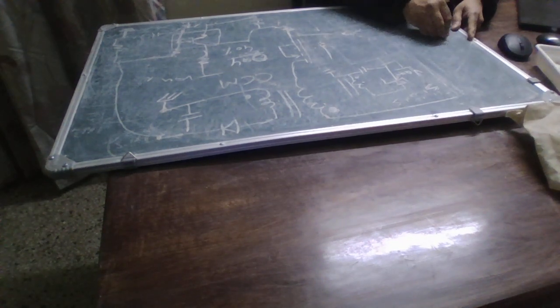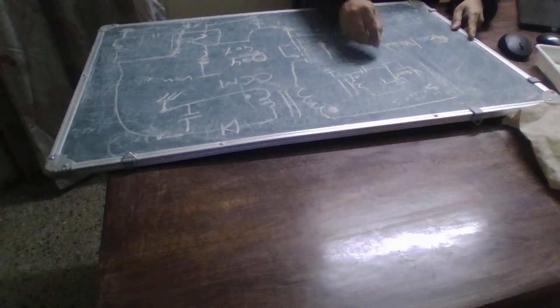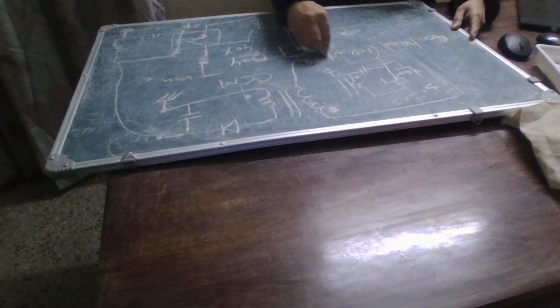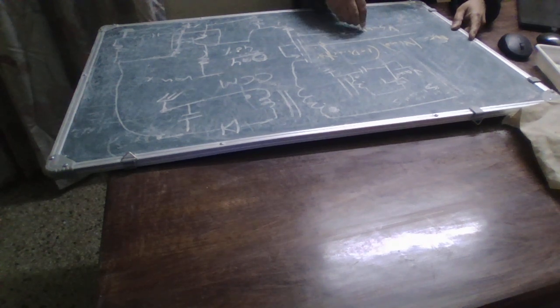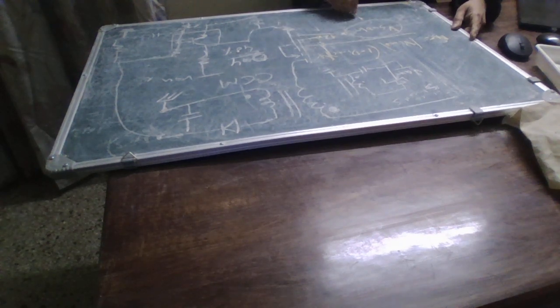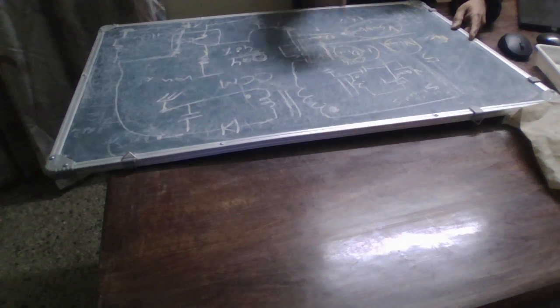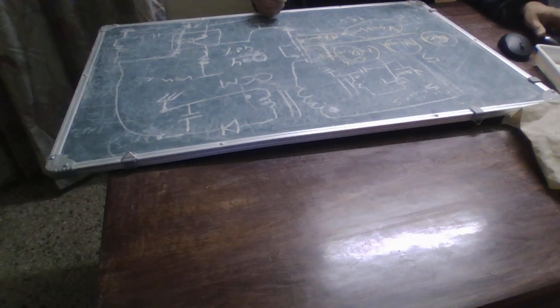We get NS equals V load times (1 minus D max) into NP, divided by V supply times D max. I am going to take the minimum supply, that was 18 volts. V load we know is 5 volts. D max we know is 0.4, which we selected ourselves. NP I am assuming here to be 1. So we know the number of turns of the secondary.